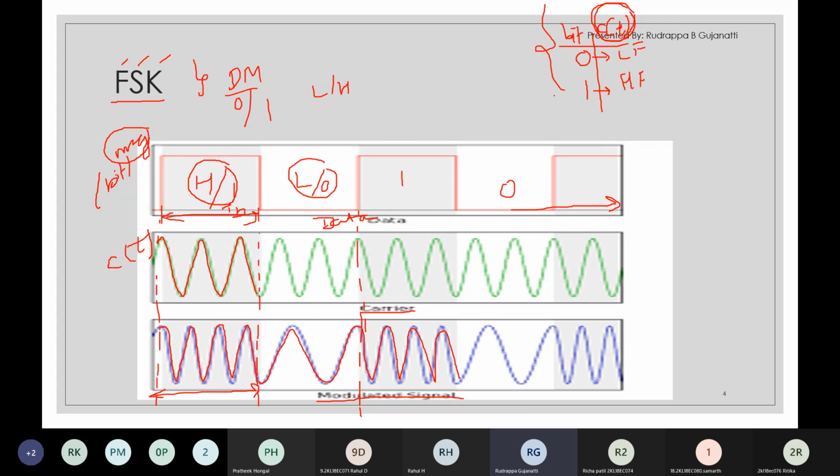The advantage is that you will be having only two possibilities: either the data will be 0 or 1. And when we are representing this in the voltage representations, as we had discussed in the previous case, we can represent it in NRZ, RZ, return to zero, non-return to zero, binary, polar, unipolar. So all those things can be considered. So this is actually the representation what they have displayed over here. So we can consider it as unipolar, non-return to zero format, what they have considered.